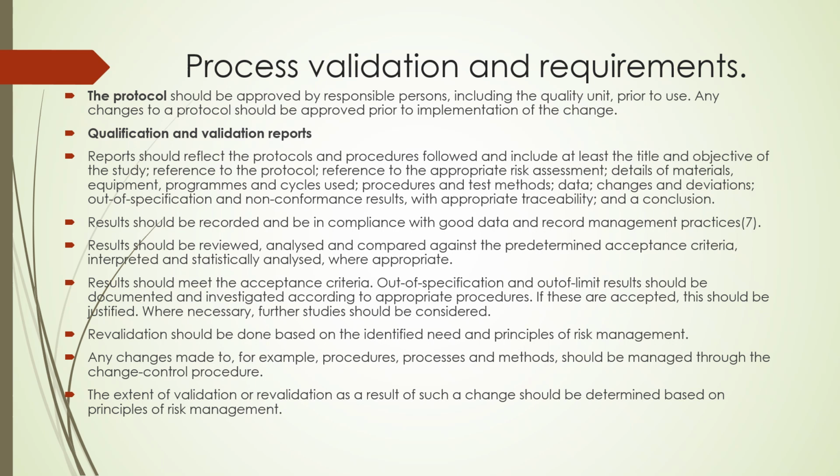Qualification and validation reports. Reports should reflect the protocol and procedures followed and include at least the title and objective of the study, reference to the protocol, reference to the appropriate risk assessment, details of the material and equipment, programs and cycle, use, procedures and test methods, data, changes and deviations, out of specification, non-conformances results should be mentioned. Appropriate traceability and a conclusion should be mentioned.